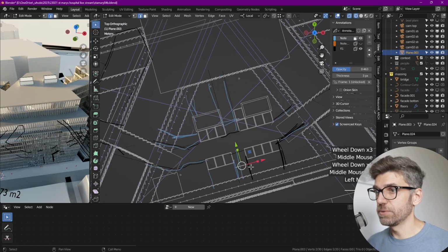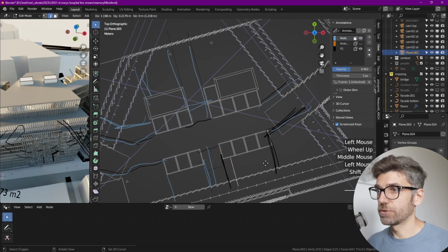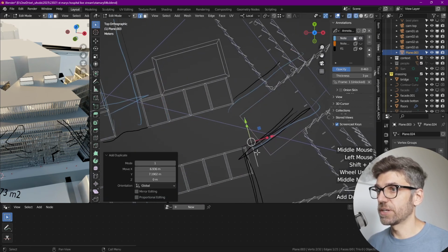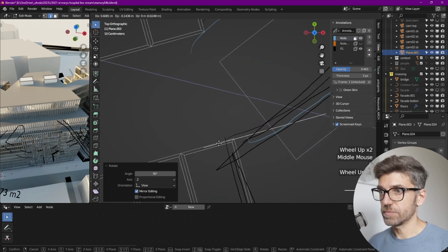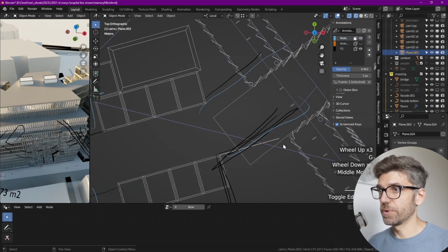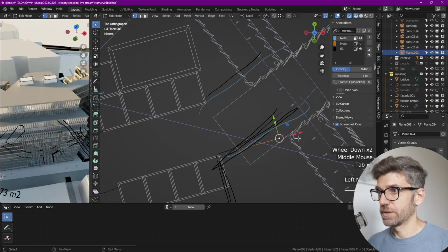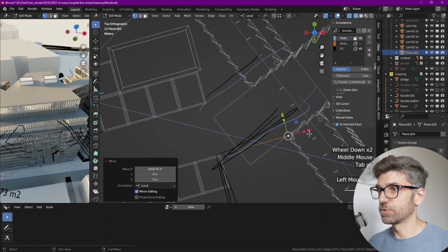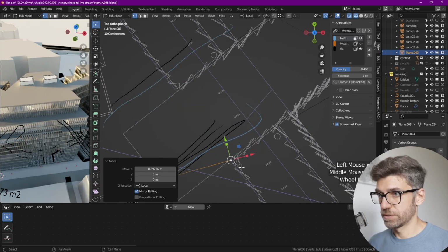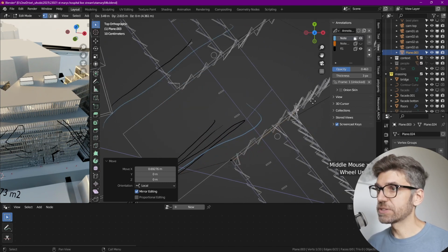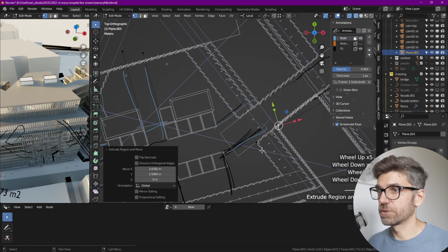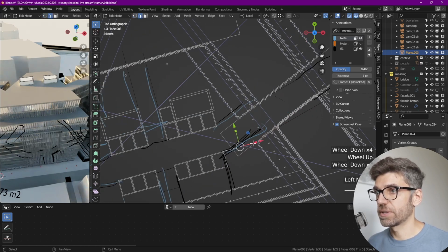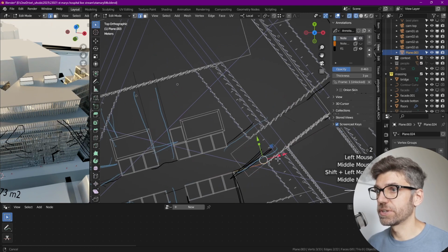So let's continue. I'm going to duplicate that wall over here and rotate it 90 degrees. Snap it to that point. And then it needs to come to wherever this bridge is. We want to be a little bit outside of the bridge, so the massing has an easier time when we're intersecting those walls. Great, so that's that edge over here.